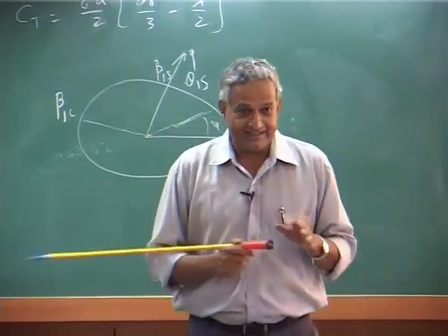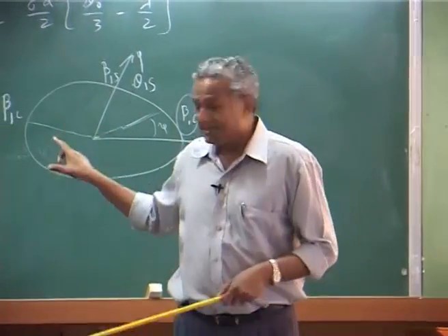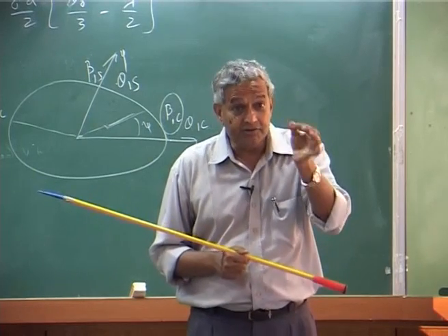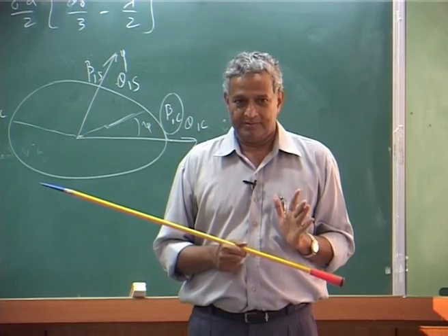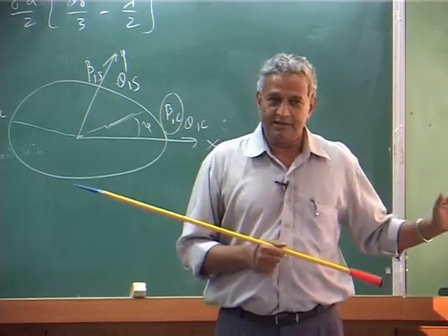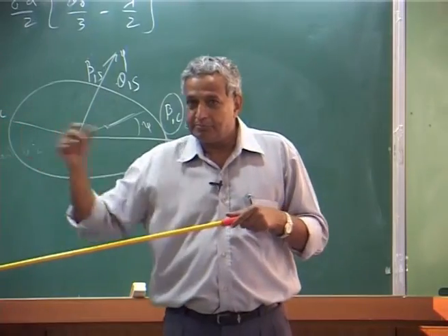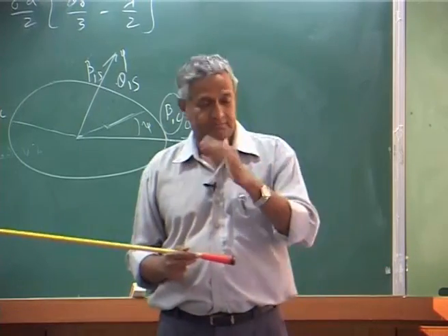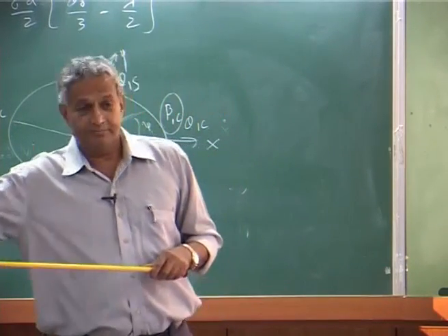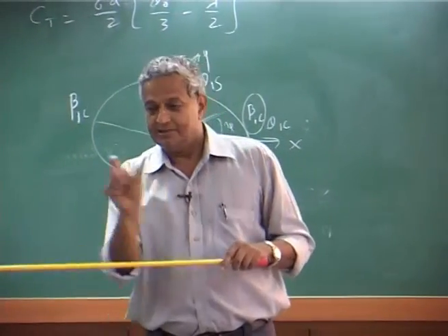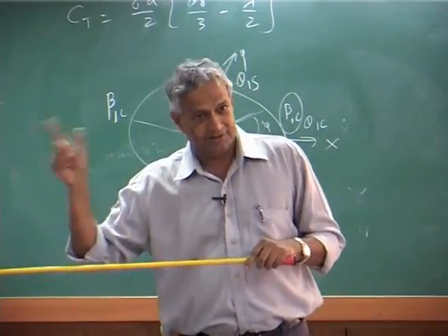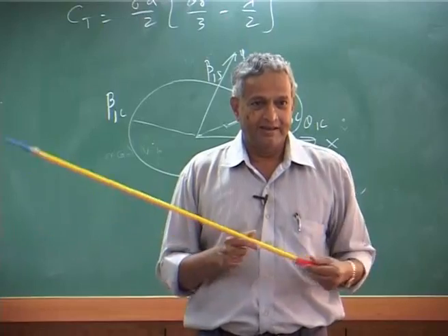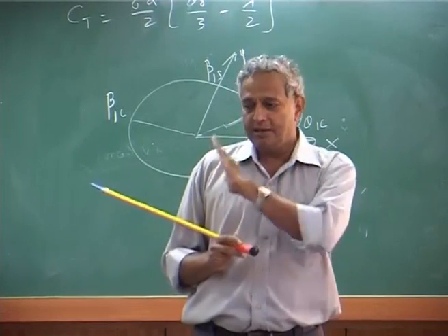But please note, this 90 degree is only for this simple case of hover plus centrally hinged blade. It will vary the moment I have a different flap model. If I put a spring, it will not be 90 degree, it will change. If I put something else, hinge offset and a spring, it will change. Then how it changes, that is what we will derive, the phase shift between input and output.